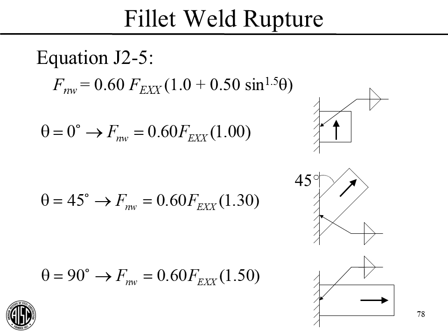You can go back to our equation for the weld strength, and you see our directional factor in parentheses, and it's a function of the angle. If we have 90 degrees for that factor, it is greater; if we have 0 degrees, we only have 1. So yes, that is correct. All right, good job everyone.